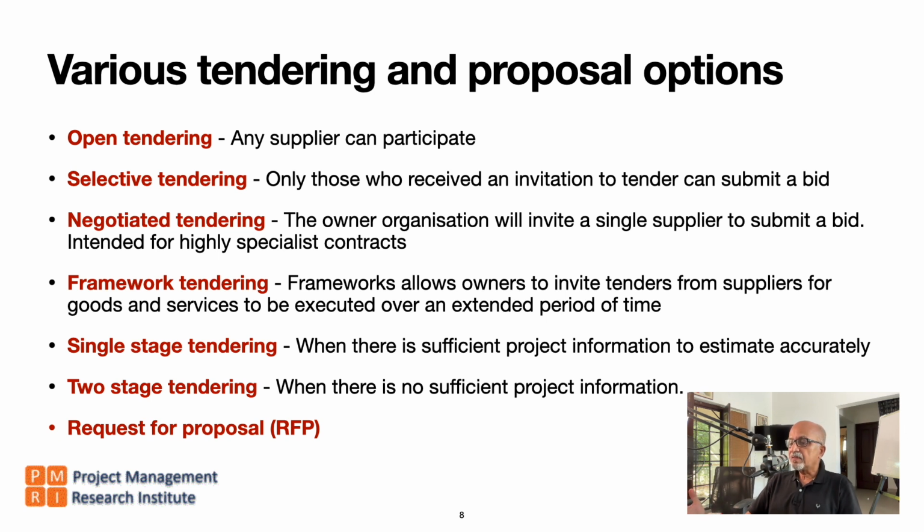So if the project duration is very long, and if you want to make use of the same contractor for a similar work till the completion of the project, then this is the best form of tender, framework tendering. So we close the tender once and then start working with that particular contractor throughout the project.